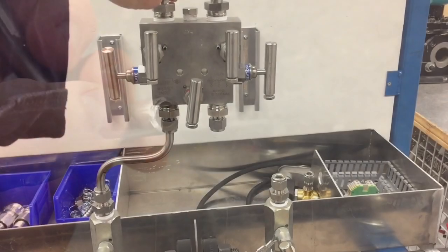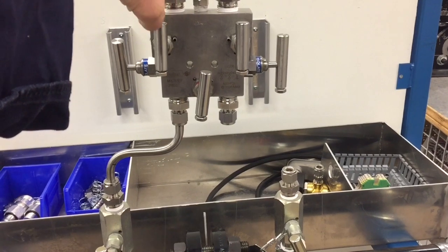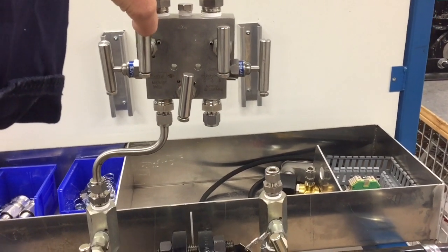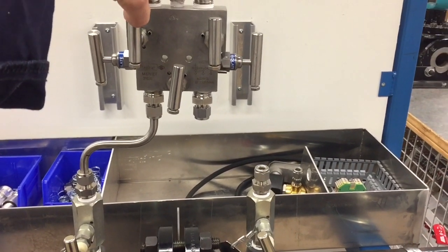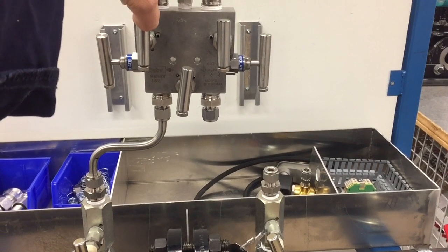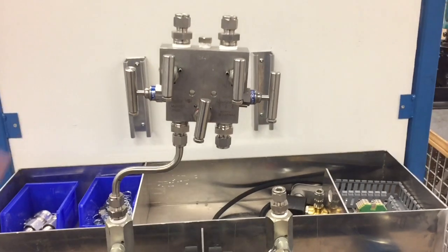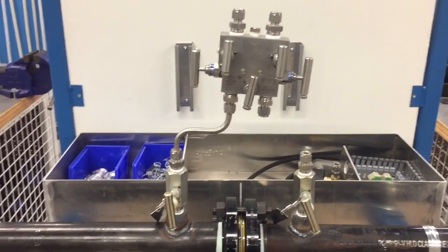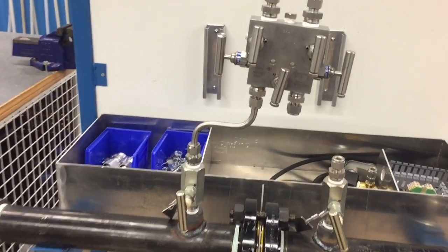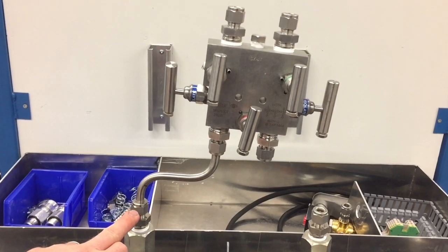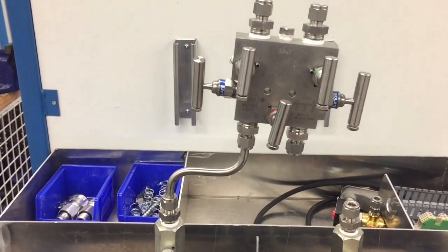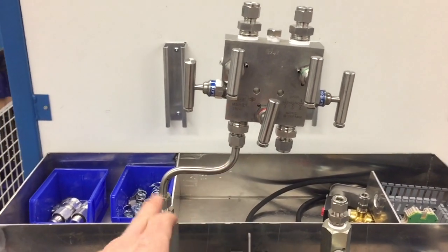When we're installing our tubing, I've placed the tubing in. I haven't tightened the nuts yet, but just to do a quick visual check, it looks like it's going to put us pretty well right in the middle of the 2 needle valves. Once we get the other piece of tubing in there, it'll support it as well, because when I let go of it, it sags off to the side there. But I'm going to tighten the nuts for here and here, so this piece of tubing is then complete.